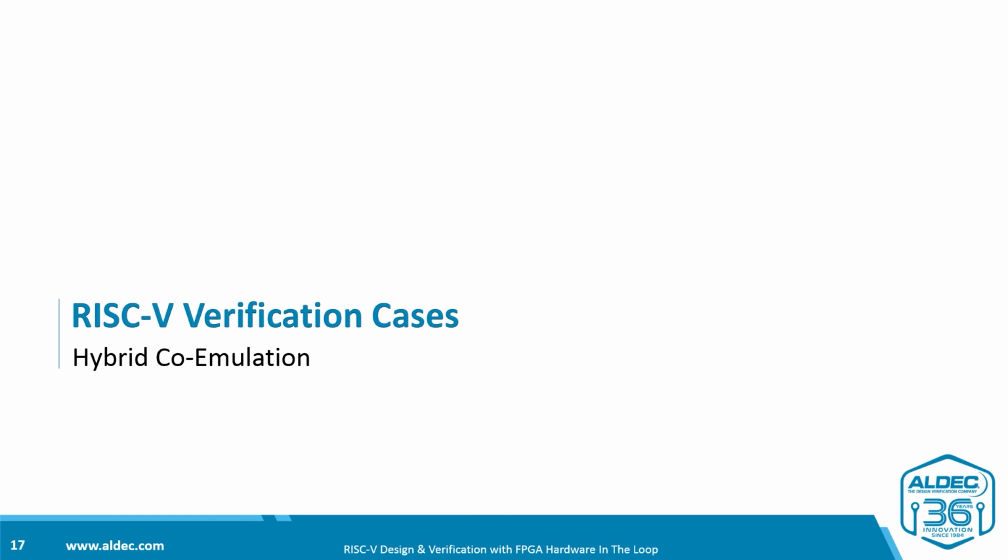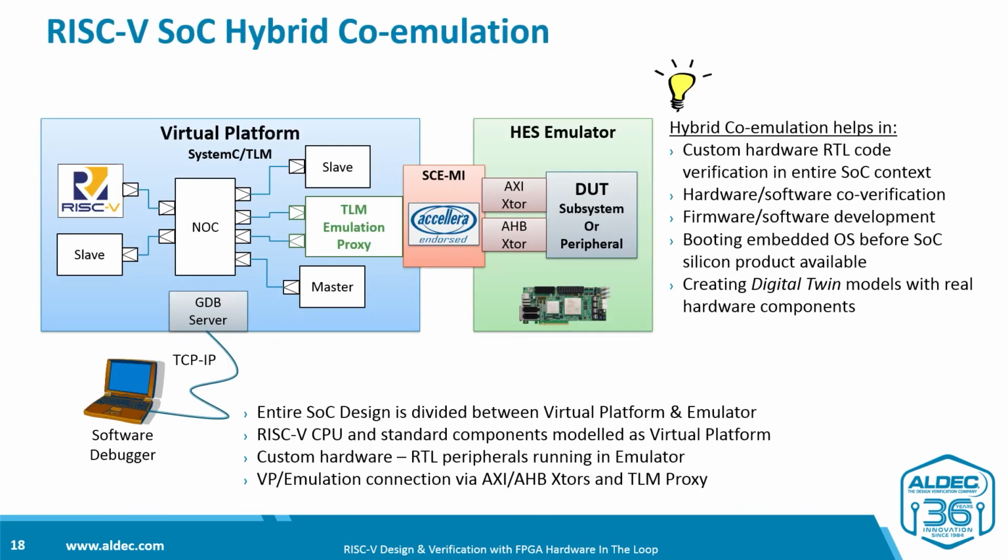Now let's review the hybrid co-emulation case. Let's start with defining the hybrid co-emulation term. Hybrid co-emulation is a mixed hardware-software emulation approach where part of the SoC is modeled as a virtual platform, and some other parts or subsystems are running in the FPGA emulation board.